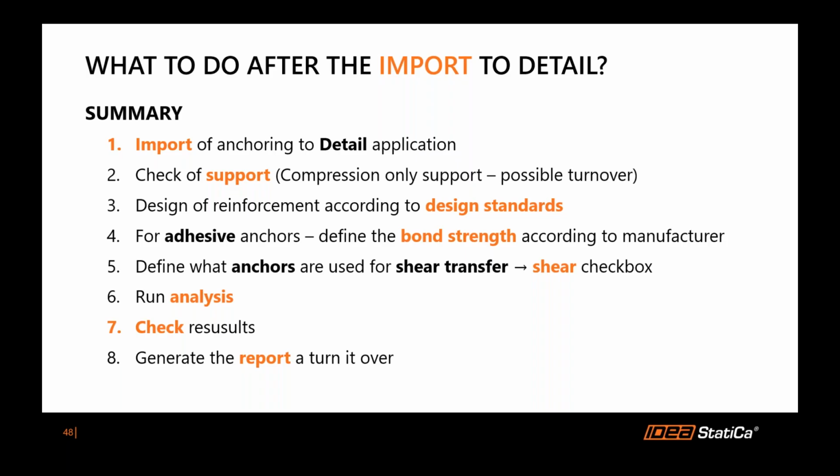This should be done according to the standards. There are requirements you are probably aware of. For adhesive anchors, you need to define the bond strength. It was talked about many times during this webinar, and it is always necessary to check the transfer mechanism for shear loads. There's a checkbox for that.